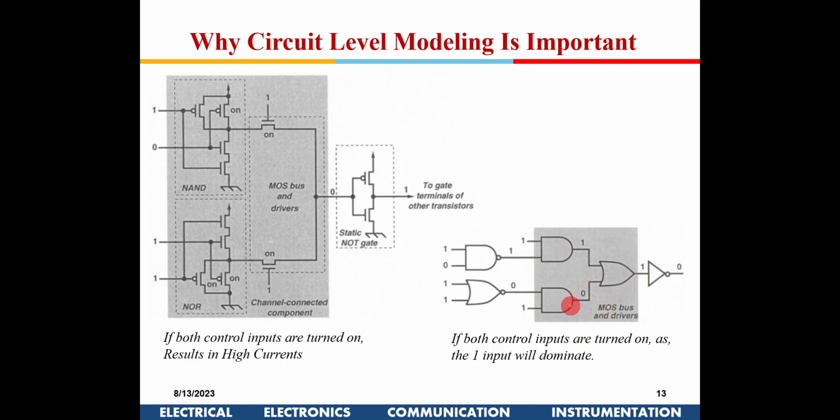If I give a gate-level description and ask the tool to implement it, it can implement the MUX like this. Now how is it working like a MUX? See, this is a NAND gate, this is a NOR gate. So there is no problem with that. If I write a functional line for MUX, it could get implemented here.